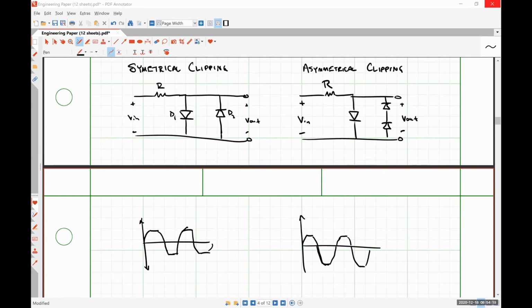For instance, a 130 ohm resistor, I think, is a standard value, and probably costs somewhere around a nickel. A custom made 137 ohm resistor would probably cost somewhere on the order of $8 to $10, right? So I want to see that the component values you use for your circuit design are things that are widely available and that we could order. Also take into account power ratings and things like that. So if you used a 1/4 watt resistor and your circuit analysis simulation tells you that the resistor is going to be absorbing 2 watts of power, what does that mean?